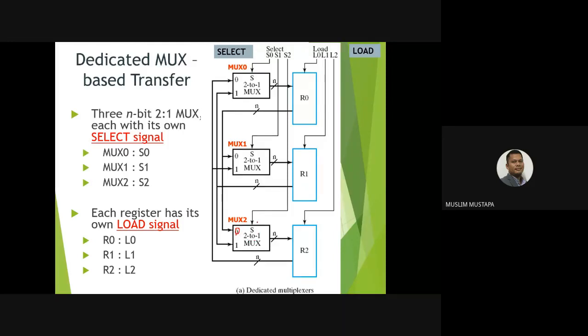Here's a 2-bit selection, so you just choose 0, and then it's going to feed data from R0 into R2. Same goes if you want to move, let's say, R2 to R1. You just follow the line, R2 goes to R1 on line 1. So you send the value 1 here, you select input 1, then the value from R2 will go into R1.